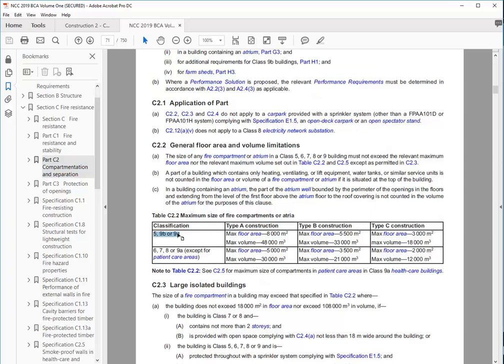So I think you could just... That's right. So for the bottom level, if you want to, you can put the area of the ground floor and show that fire compartment is under the requirements. It will be, because look how big they are. Look at those sizes. Do you have a rough idea how big 5,000 square metres is? It's bigger than this campus. Right? So your building is a long way under that requirement. So normally this is something you check. If it's a large building, you would always check this. But for smaller buildings like this, it's not that relevant.